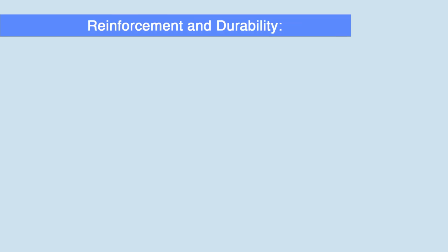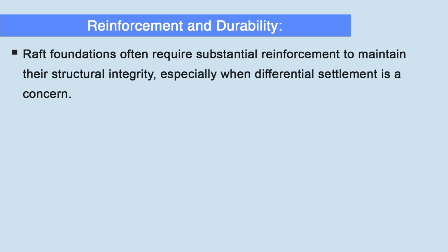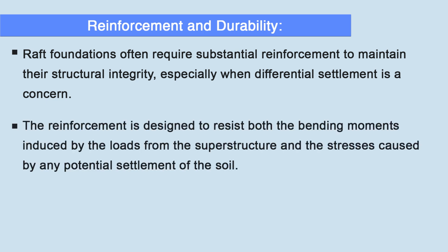Then the next is reinforcement and durability. Raft foundations often require substantial reinforcement to maintain their structural integrity, especially when differential settlement is a concern. The reinforcement is designed to resist both the bending moments induced by the loads from the superstructure and the stresses caused by any potential settlement of the foundation.